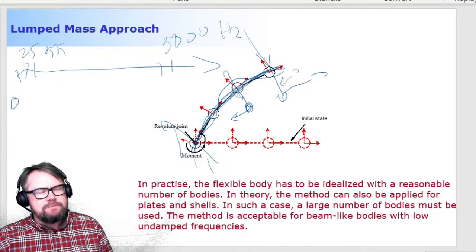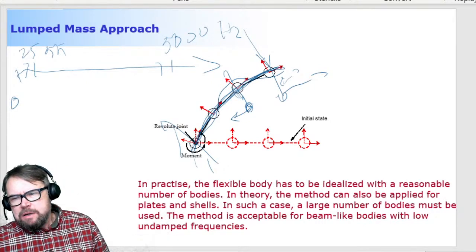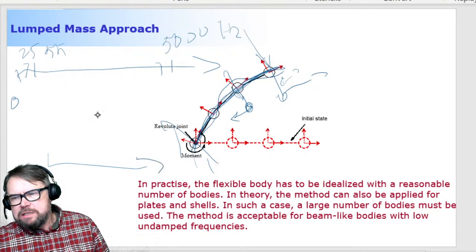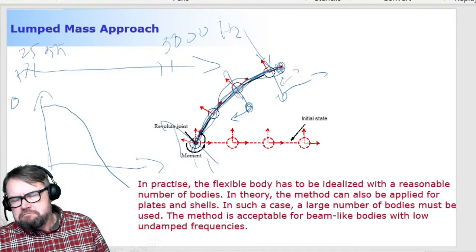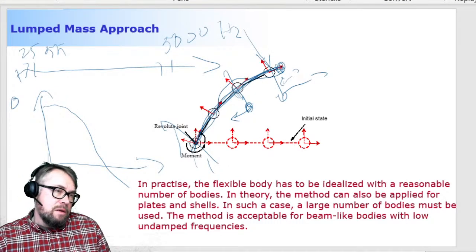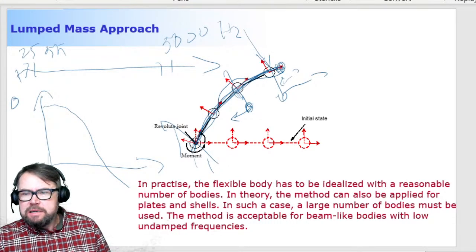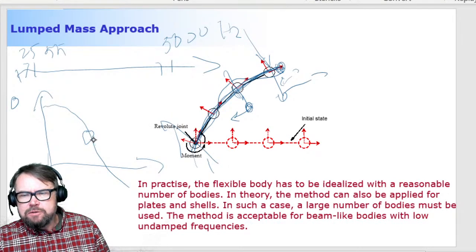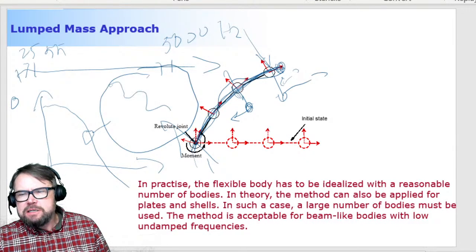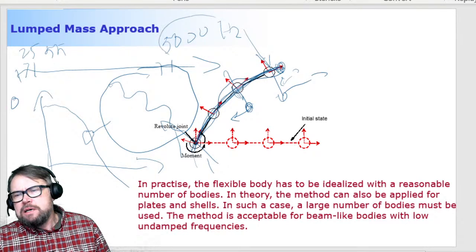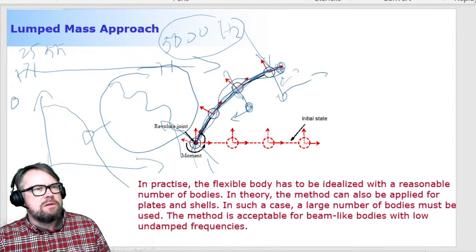What is the problem here? The problem is that when you are solving the response, let's say the free end of this cantilever beam looks like this. There are no surprises. But if you make a magnification about this point of the curve, you can see that there is this high frequency due to the high natural frequency.